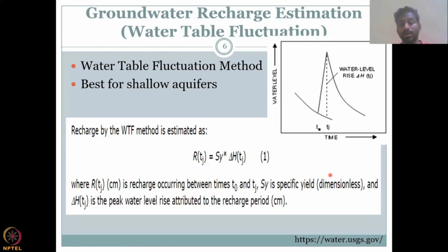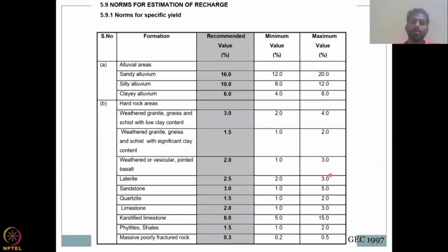It tells about how much water can actually flow through gravity, and the remaining water is available for plants and stuff. So here the most important factor is not only groundwater data, because you need to have a lot of data accumulated over time, and sometimes you do have meters which are monitoring these data at a longer time interval. The most important factor is the specific yield. It's very, very hard to estimate and expensive.